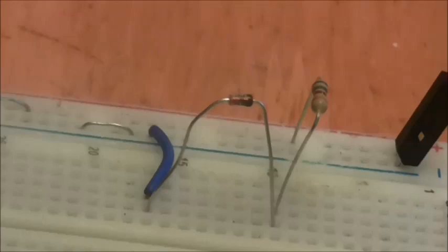So what we looked at previously is how to regulate an incoming voltage in its waveform, and we've seen that we can use a barrier or a Schottky diode to turn an AC waveform into a DC. What we're going to do here is we're going to use a thing called a Zener diode, or you might possibly hear Zener, that's the American way to pronounce it, to turn a DC supply of a given voltage into another DC supply of a different voltage, and the voltage that it turns into depends on the voltage for the Zener diode.